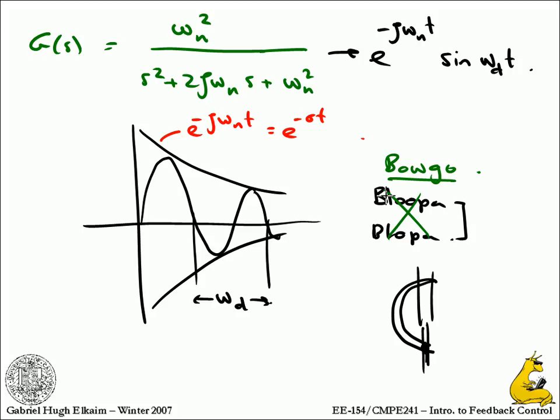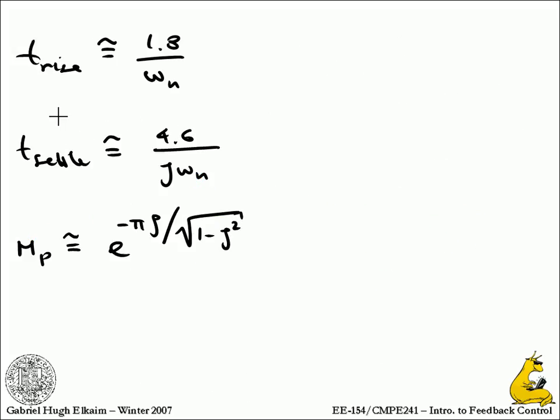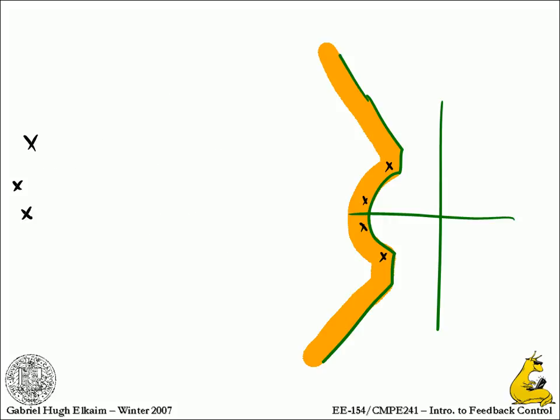So once we have those time domain specifications, we now know, at least approximately, how to relate these back to our complex plane specifications, which gives us an area of where I want to put, basically a keep out area of where I want to put my poles. And then what I'm going to do is say, well, as I said, putting them way over here has implications. So generally you want to hug the boundary as much as you can. You don't necessarily have to be right just to the left of the boundary, but in the general vicinity of the boundary is probably the best place to go. And then you're going to work it out to move your poles there, and then you're going to simulate the system and say, okay, does it actually get there or not?